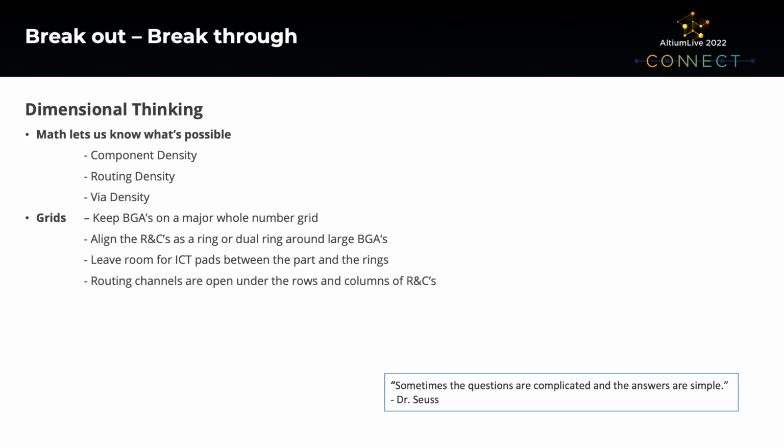And then the IC, routing the power into that, usually we want to bring that from one side or two sides, and let that power come in from one side and try to eliminate our other circuitry from blocking the power from effectively supplying that BGA. BGA changes are probably one of the harder PCB changes there are, because the signals from that go all directions. They're not easily put into rows, and the escapes are harder because there are multiple rows and multiple layers involved.